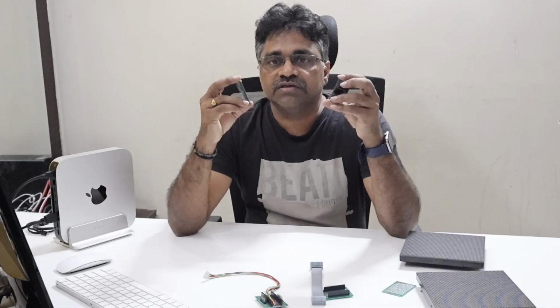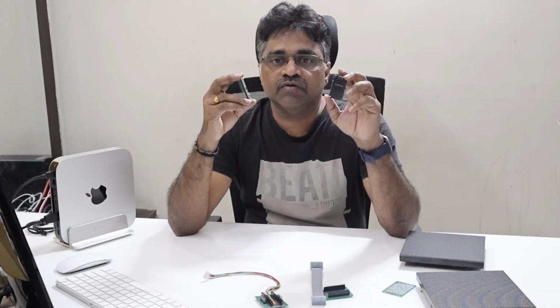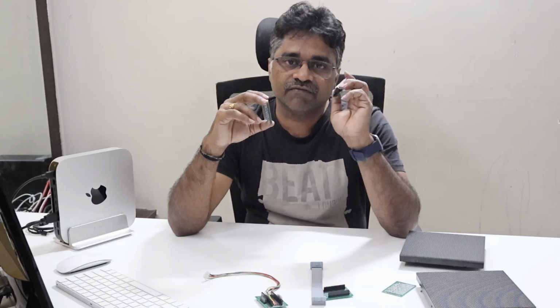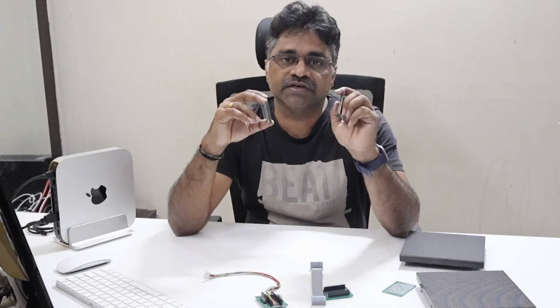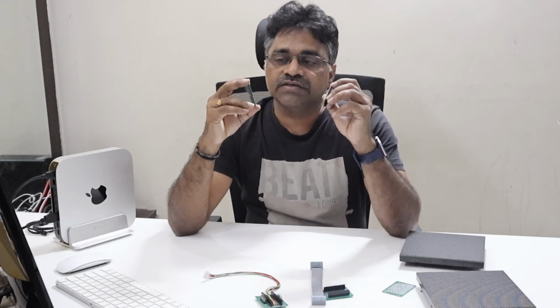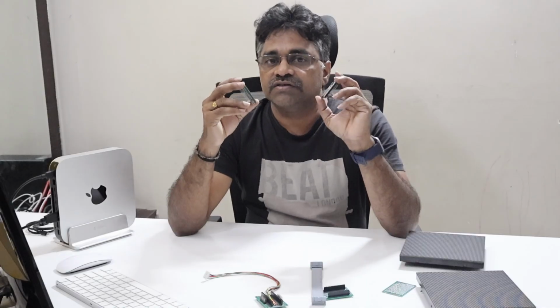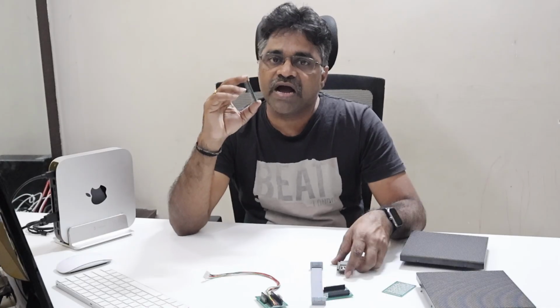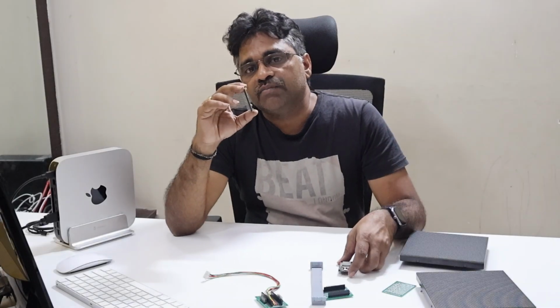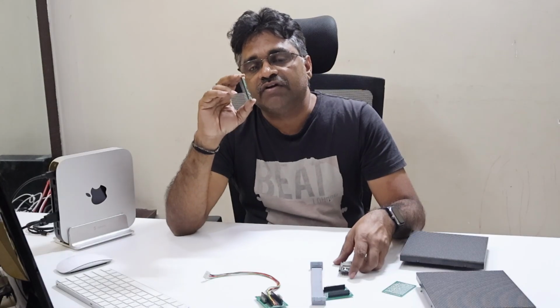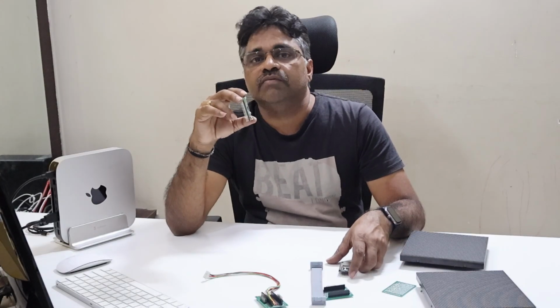For the communication between these two, I want to establish an SPI interface. The ESP32 prepares the final frame buffer to be displayed on the screen, then sends it to the Raspberry Pi Pico over SPI. Whenever the Pico receives the frame buffer over SPI, it updates the back buffer. Once it has updated the back buffer completely, it swaps the buffers, which means the front buffer is updated from the back buffer.